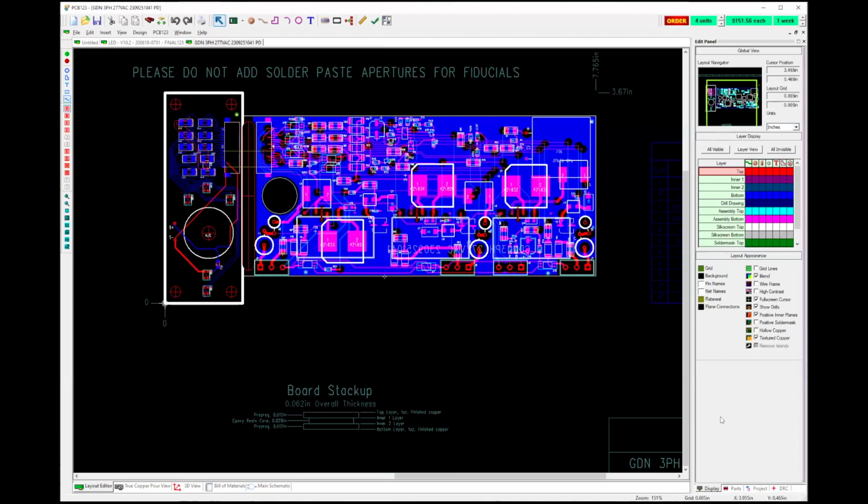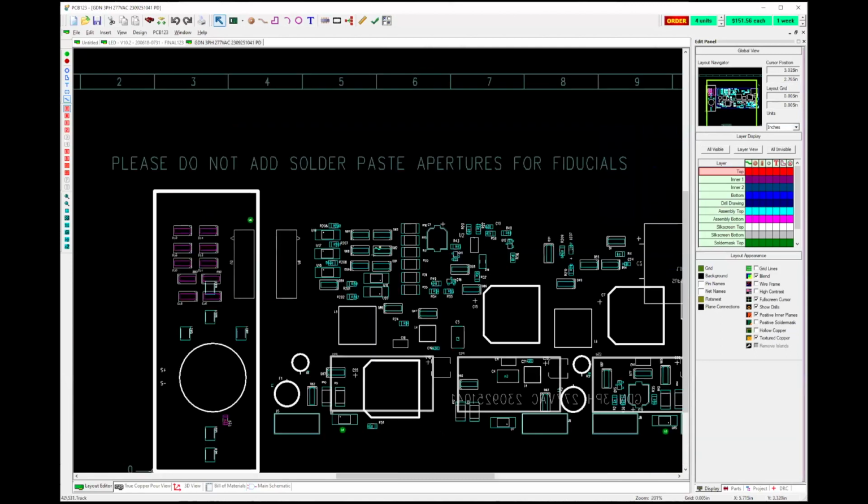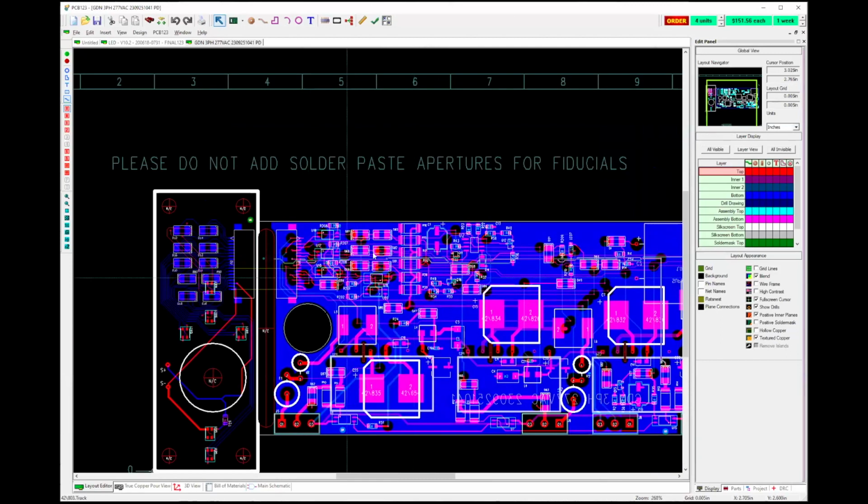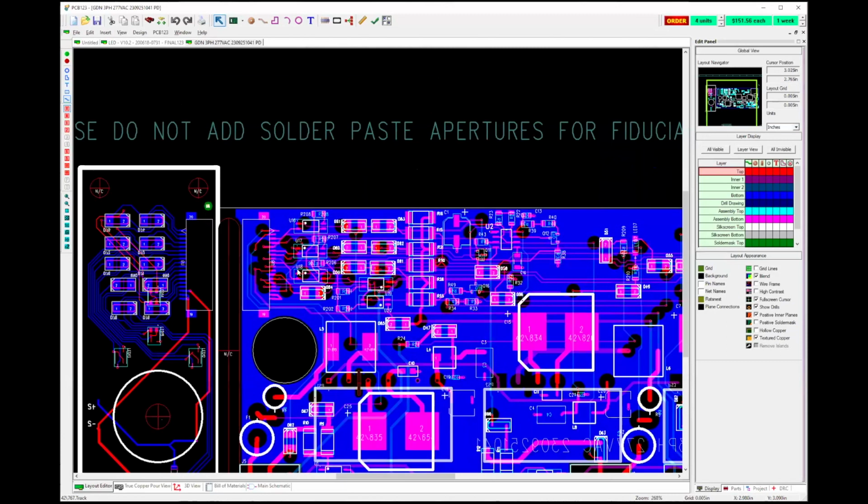Then if I've got any clocks or critical high-speed wires, I hook up those to make sure that there's room to get them hooked up and logically laid out in a way that they're not going to be interfered with by other things. And then I go in and route any other non-critical nets, just basic interconnect stuff like this area here. There's really no high speed to it. They just had to hook up.